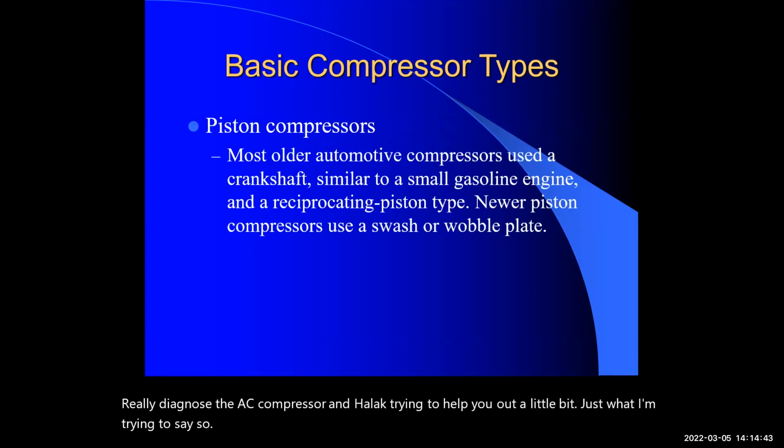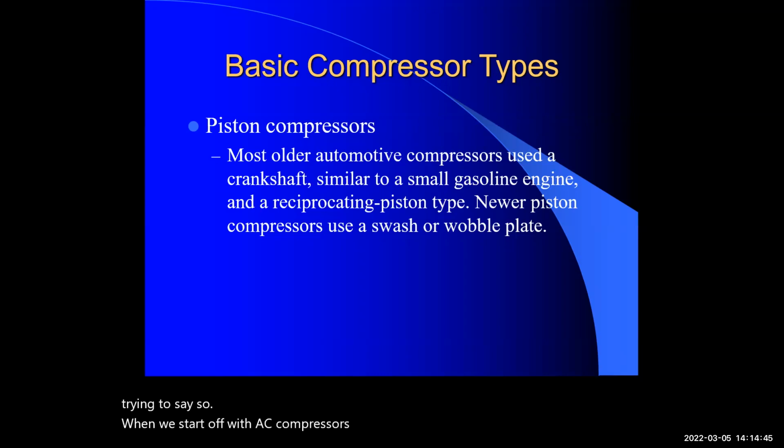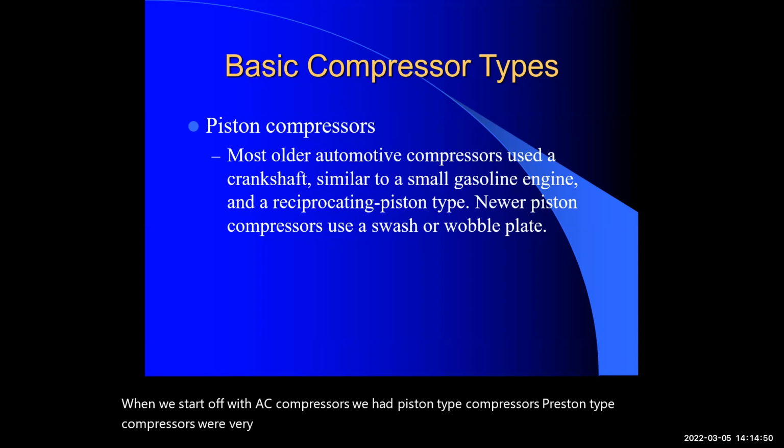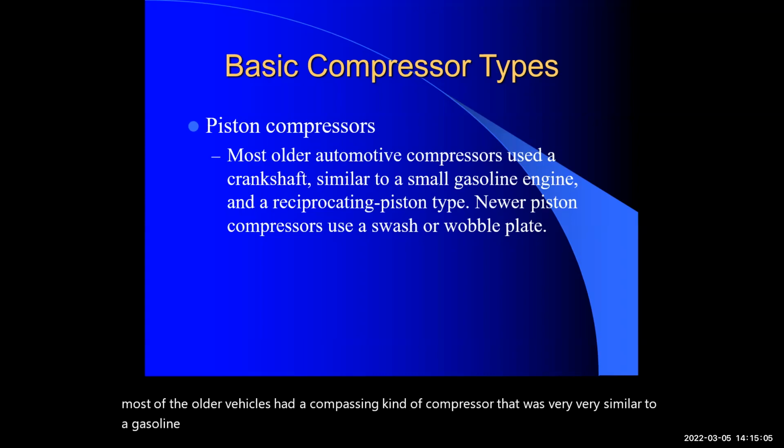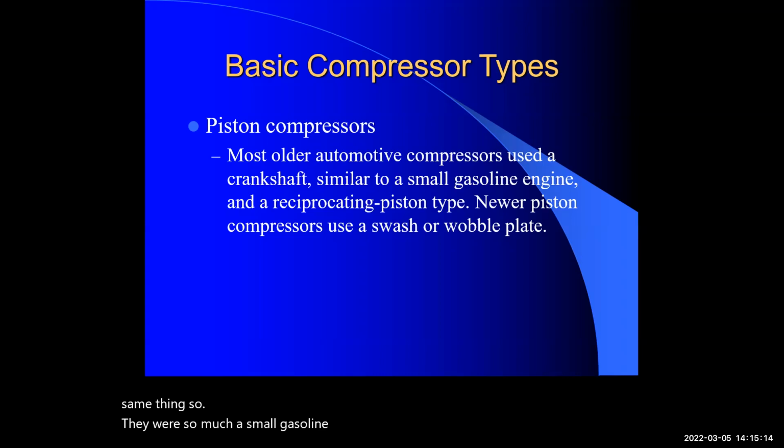When we started off with AC compressors, we had piston type compressors. Piston type compressors were very common. They took a lot of energy. Most of the older vehicles had a piston compressor that was very similar to a gasoline engine, almost like a lawnmower type engine, bigger than that, but kind of the same thing. They were similar to smaller gasoline engines and reciprocal type piston types.